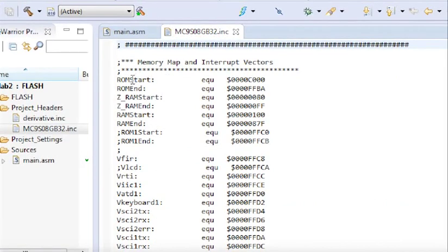Now in the memory map it says ROM start and ROM end. It tells the addresses where things begin and end, but there has been no ROM in modern microcontrollers except for 4-bit microcontrollers used for Christmas tree lights for years. When it says ROM start, ROM end, this really means flash memory. Now ROM is a one-time burn. Flash memory, you can burn it as many times as you want, and that's why with all the modern microcontrollers, if they're put into a product, you can then flash in a new version of the product, no problem. So ROM start, ROM end, these are just names that have been around for a while, but in our terms it really means flash for our microcontroller.